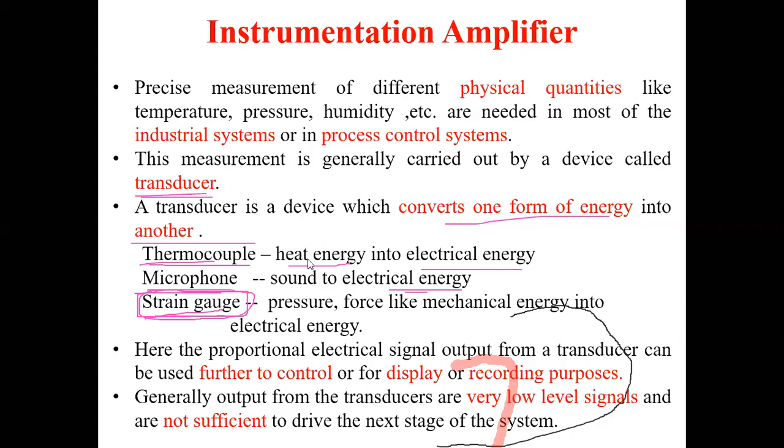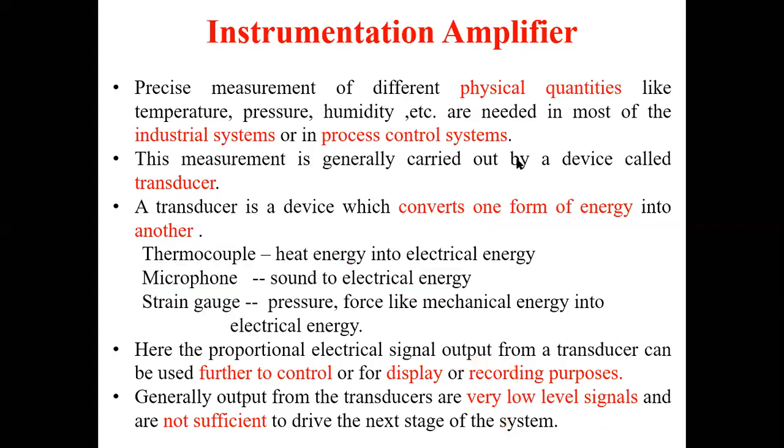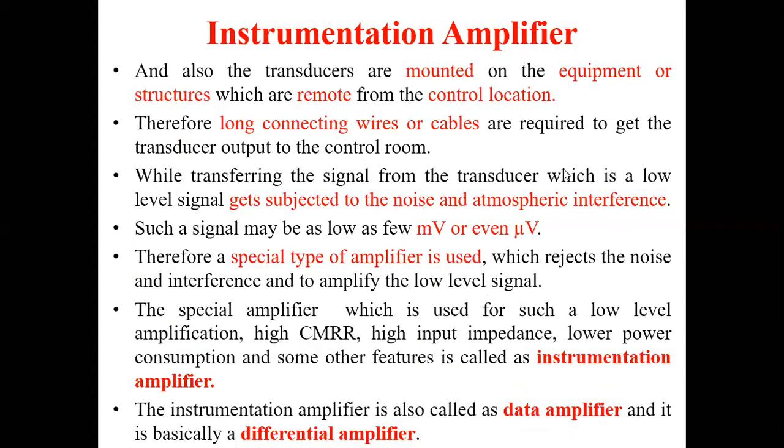But the thing is that the output of a transducer is a very low signal, in the order of millivolts or even microvolts. This millivolt signal cannot drive the next stage of the system. Also, since it is a very low signal, it is subjected to noise very quickly.